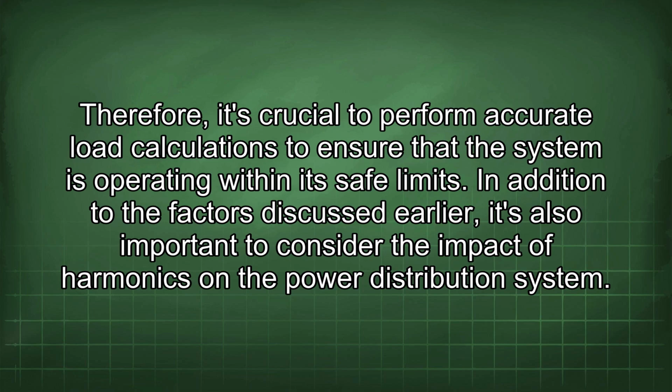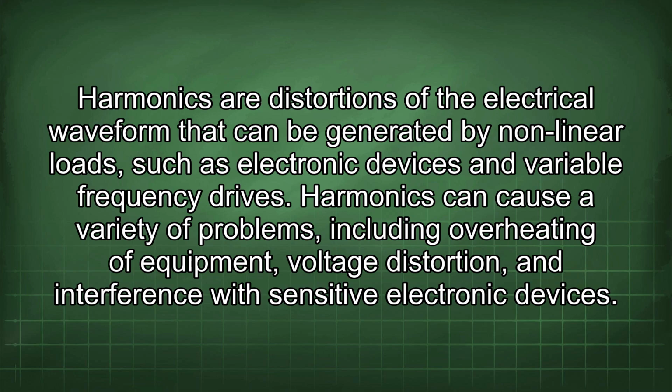In addition to the factors discussed earlier, it's also important to consider the impact of harmonics on the power distribution system. Harmonics are distortions of the electrical waveform that can be generated by nonlinear loads such as electronic devices and variable frequency drives. Harmonics can cause a variety of problems, including overheating of equipment, voltage distortion, and interference with sensitive